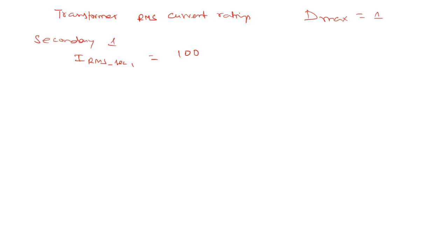So let me go ahead and draw the schematic here. So it's a full bridge, 4 switches. Okay. It's okay if we just draw the ideal switch symbol, it does not have to be a MOSFET symbol. The DC input voltage 100 to 200 volts gets connected to a primary.